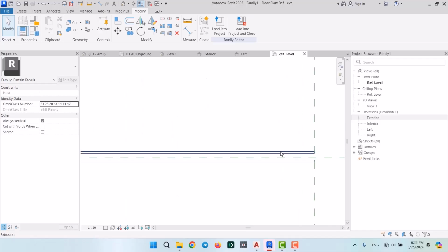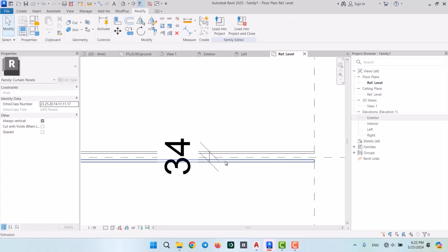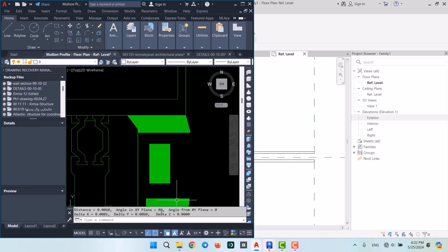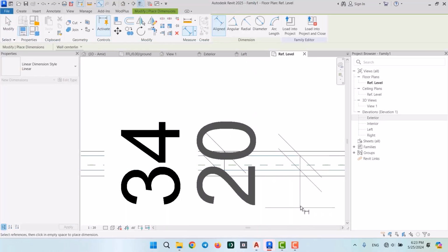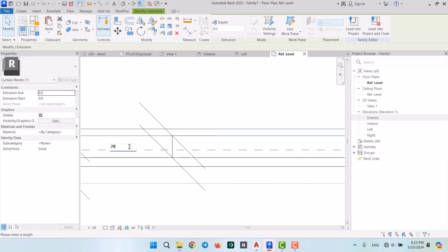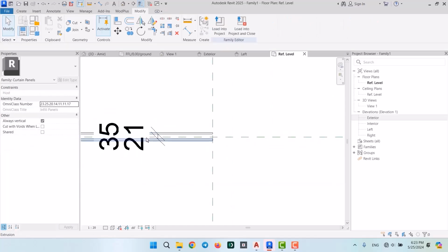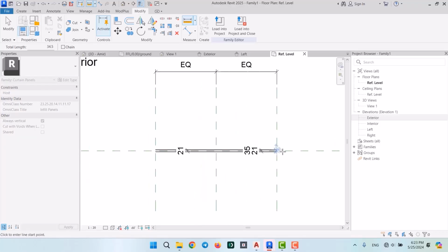So far we have created our glass panels. And now I'm going to also measure the distance between their outer sides, and it's supposed to be 34. So it's 34 millimeters long. And if you like, you could even include the decimal digits. For example, from here to here is this value, where you can see also there's a 5 at the end, which you could even include if you like. In other words, you are free to make the distance between these two panels exactly like in the CAD plan. Like you could make this 0.205. Alright, and if you remeasure the distance between the outer sides, then you will have the value that is exactly like what you have in the CAD plan.